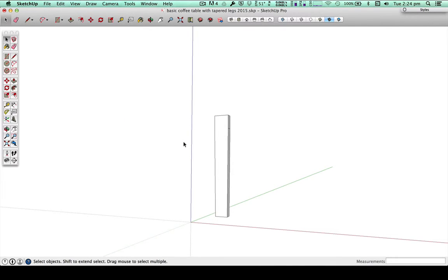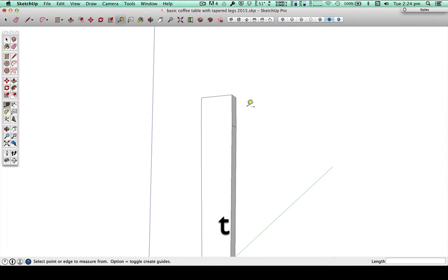Going back to, let's just pretend we wanted to edit this group, it does matter. Let's just say I wanted the material to be a little bit thinner. At the moment I think we've done a 25mm material. Say I wanted to make it 20. What would I do? Well, you would think I'd just go to the push-pull tool, click on this surface, but hang on, there's something red. I would click on this surface and try to, nothing's working. And the reason for that is that when you've made something into a group, remember this, you need to go into edit group mode.